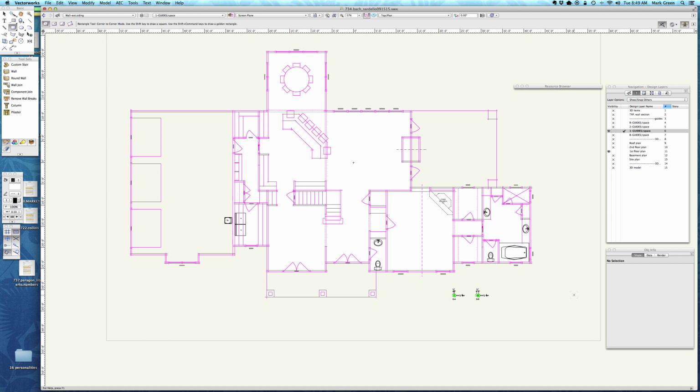To make sure everything that you draw is on the right layer and in the right class and drawn with the correct tool, the way to do that initially, in case I save the file in a way that you're not ready to draw right from the get-go, would be to go over to this tab here, which is your navigation palette. It's the Save Views tab.